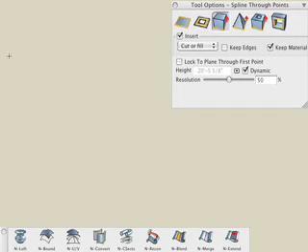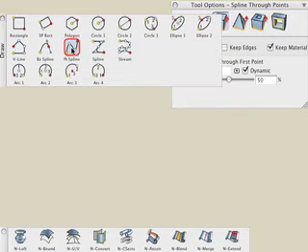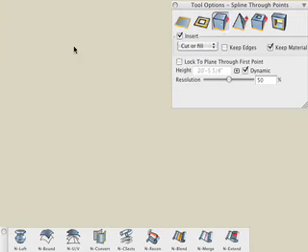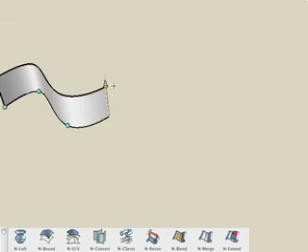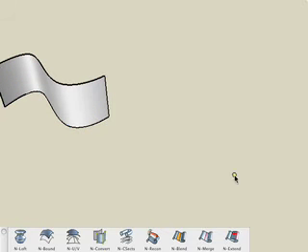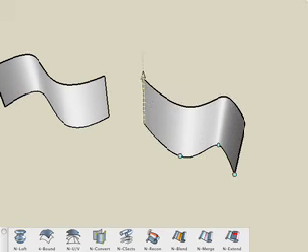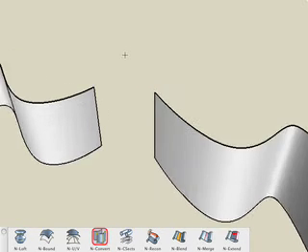We begin with 2 surfaces created by extruding spline curves. We use the spline drawing tool, and we have the 3D extrude icon selected in the tool options palette, and simply extrude a surface object. Then, with the Nurbs Convert tool, click on them to convert them into Nurbs surfaces.